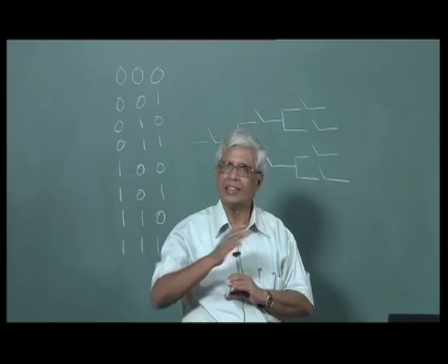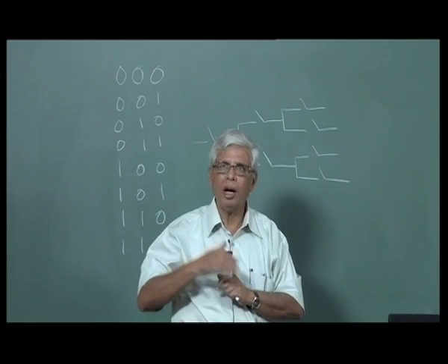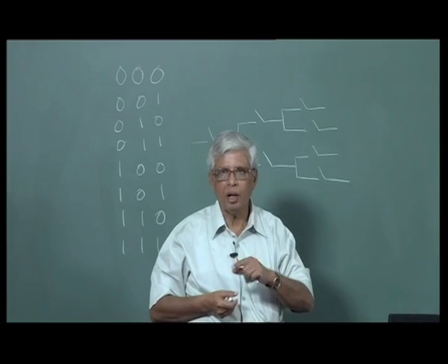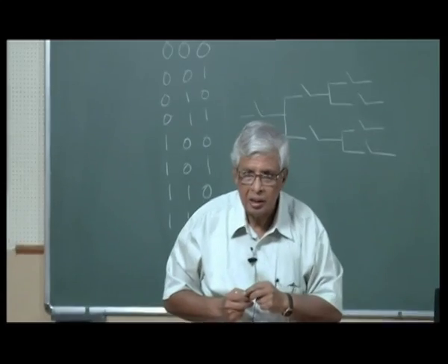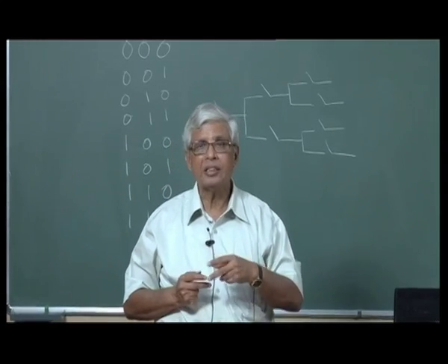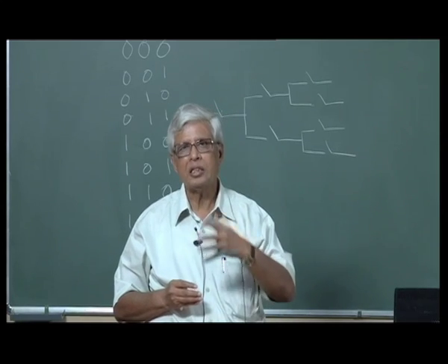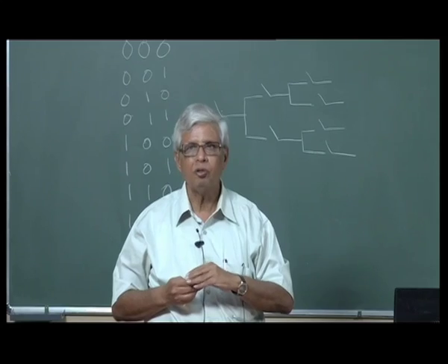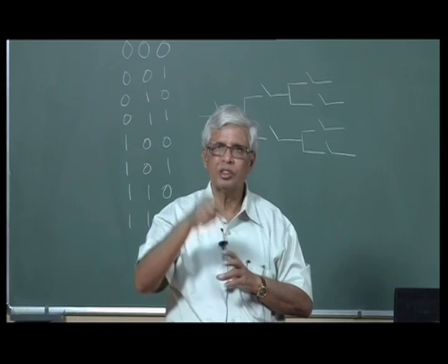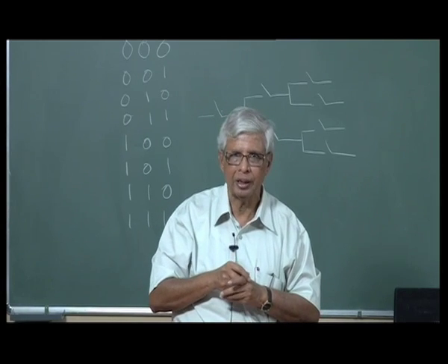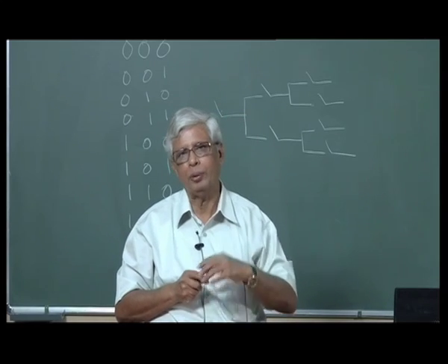Okay. So it has nothing to do with bandwidth. The levels can be determined by how accurate you want it. Do you want only 1 bit? That means only 2 levels are possible in the measurement. Do you want 2 bits? 4 levels are possible. 3 bits, 8 levels are possible. 4 bits, 16 levels are possible, like that. So whether we really want the quantity of measuring to have 16 divisions, 32 divisions, 64 divisions, etc. will be determined by need. You should not have more than what you require. At the same time, you should not have less than what you require.